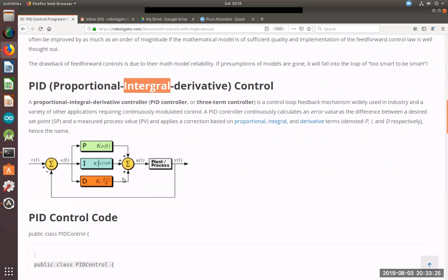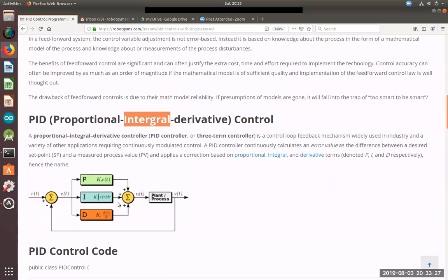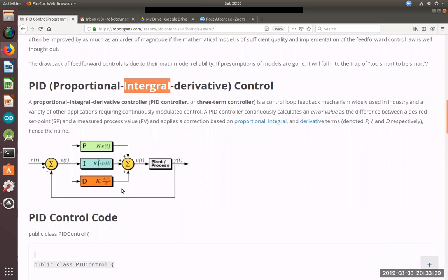All right, now how do we implement the PID in code? It's straightforward. You first find out what your error is. Basically, you have a target value. If it's travel by distance, then the error is how far you traveled versus your target. Then the delta is the error. If you make a turn, then the number of degrees you miss is the error, right?